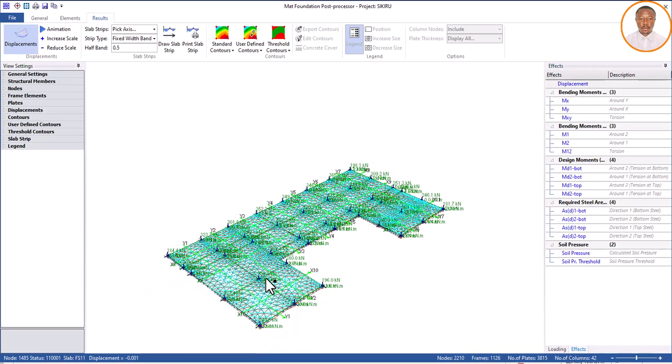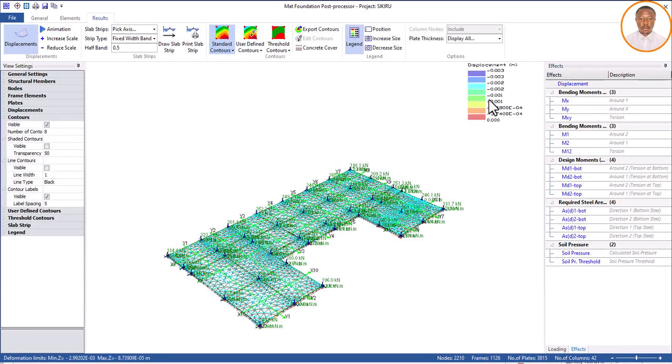So once we come to this place, the next thing we are going to do is to click on standard contour. Is that okay? I click on it and wait for it. So you can see it now. At this point, you are going to load all of this into this structure. So the next thing I'll do is click on load this bending moment. We have to load it in this MX direction inside this structure. Is that okay?